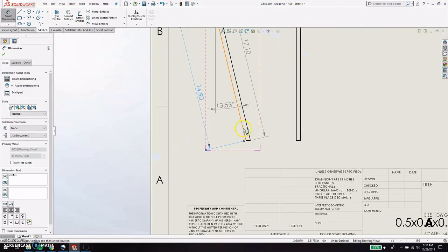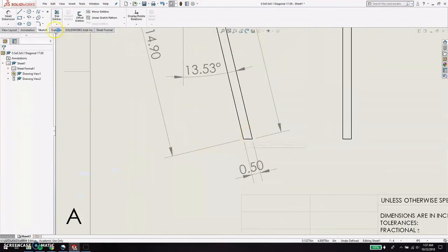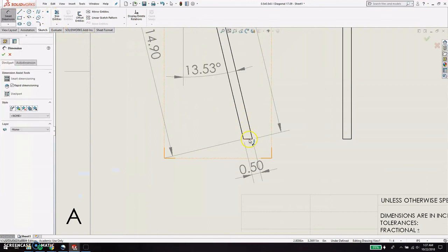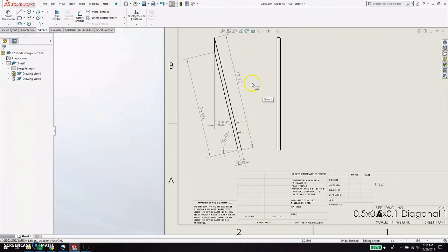Yeah, they'll be able to tell that this is a ½ inch because you'll do this, right? That shows that this is a ½ inch. And then, yeah, just make sure you show all the dimensions, all things like that, so that whoever's making this literally can't make a mistake because of your drawing. And they don't have to ask you for questions. They can literally just do it. So yeah, that's all the dimensions for this guy.